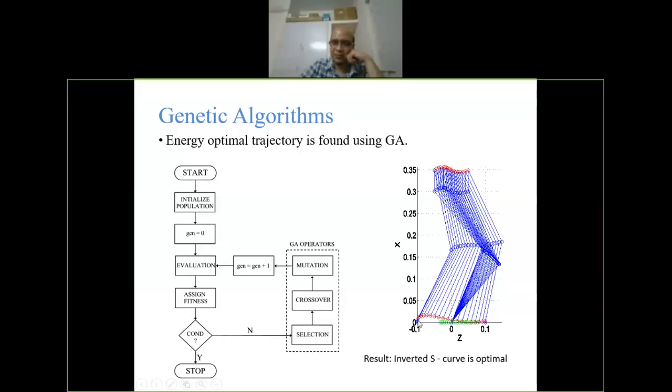So the rear foot goes up, then it comes down, and then remains parallel to the ground, and then comes to a stop. Now the interesting part here is that in our legs we have 16 degrees of freedom. Each leg has 8 degrees of freedom: 3 at the hip, 3 at the ankle, 2 at the knee. So two legs have 8 plus 8, 16 degrees of freedom, which means you have infinite solutions for inverse kinematics. So theoretically, when human beings walk, we should walk differently.